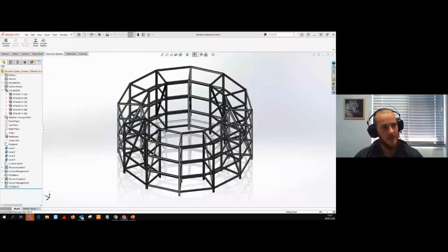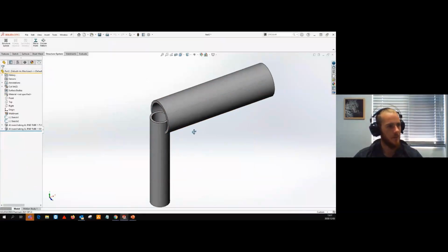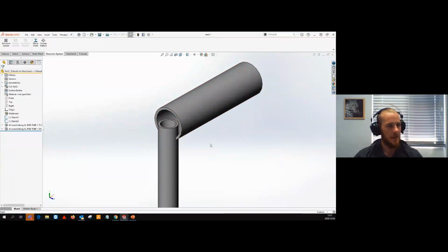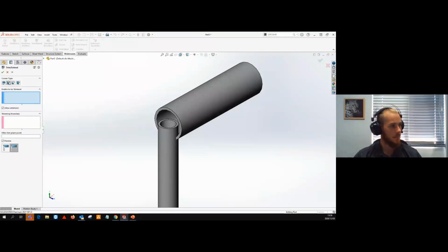So as mentioned, this is a new enhancement in 2021. If you deal with a specific design structure like this, please bear in mind that these pipe diameters are different, so they're not of equal size. If we move over to the weldments tab and I hit the option to trim or extend, you guys will notice it's very specific to the end miter option, and I'm clicking on that option there now. So this does not come into play with every type of trim extend. It's just got to do with that one over there.